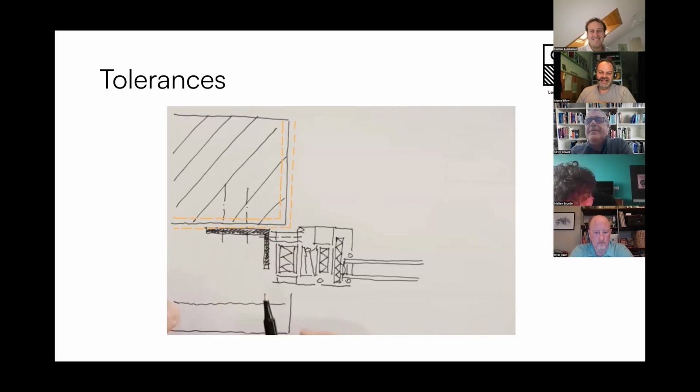Yeah, precisely. Of course, if you have your facade in the structural elements or within the line of the concrete, for instance, or the masonry wall, then you have to make sure that the window is for sure smaller, because you can't fit the window if the opening is not perfect. So that's what has to happen in order to make sure that the opening has the right measurements. Otherwise, you won't be able to move it back and forth. So it always has to be smaller in dimension.